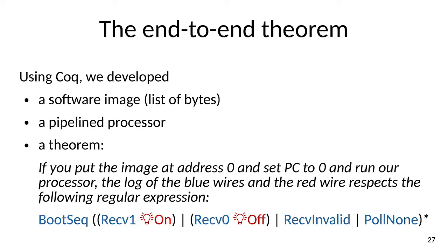Using Coq, we developed a software image, which is just a list of bytes, and a pipelined processor, and a theorem, which says that if we put this software image at some address, which we chose to be 0, and then set the PC to that address, and then run our processor, then the log of the blue wires and the red wire will respect exactly the regular expression which I presented before.